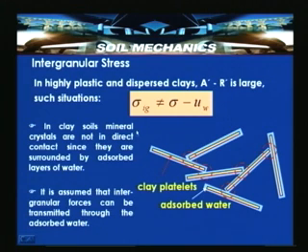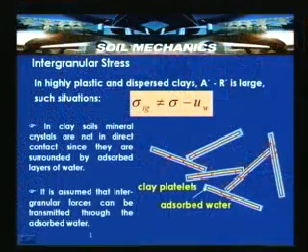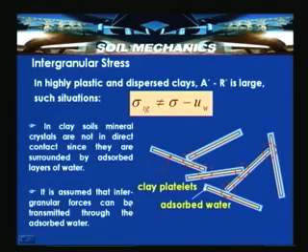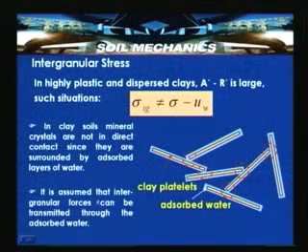So, in the clay soils, mineral crystals are not in direct contact since they are surrounded by the adsorbed layers of water. So, the mineral crystals are not directly in contact to generate the stresses, but they mobilize in tune with the adsorbed water surrounding the platelet particles. It is assumed that intergranular forces can be transmitted through adsorbed water. In this particular case of clay soils, where the difference of A dash minus R dash is very large, this type of arrangement is possible.